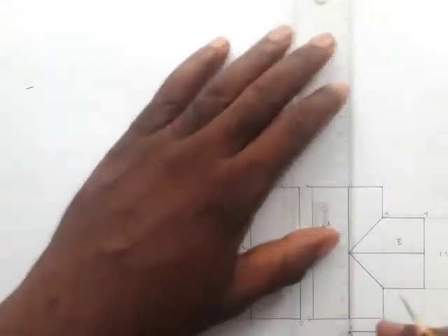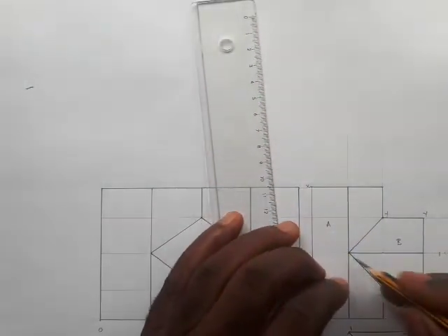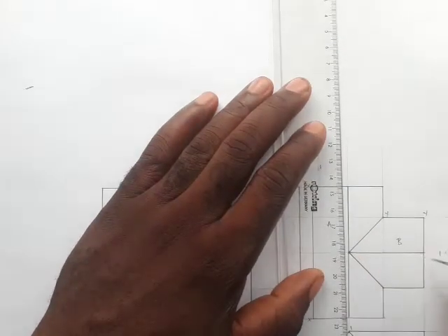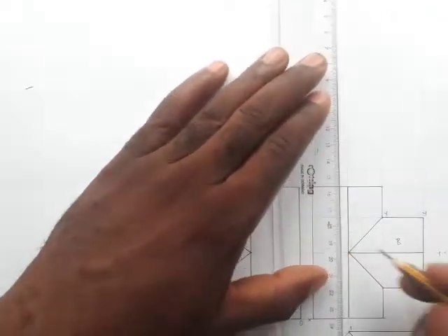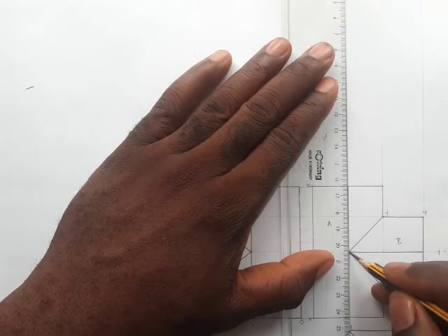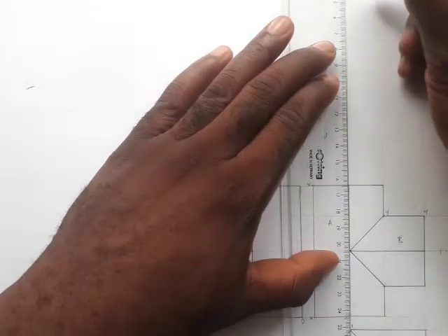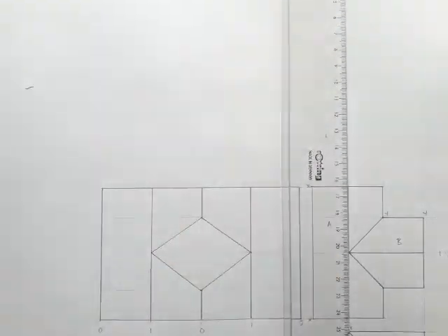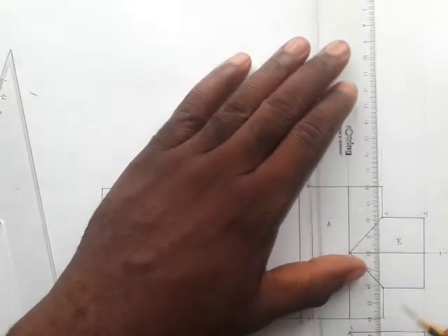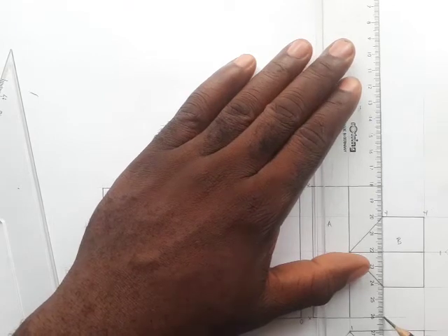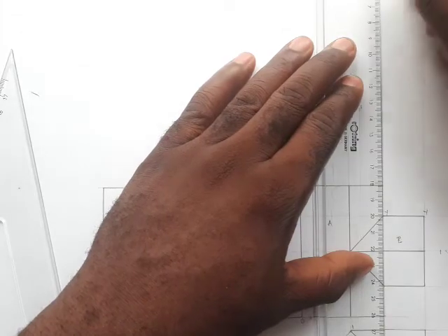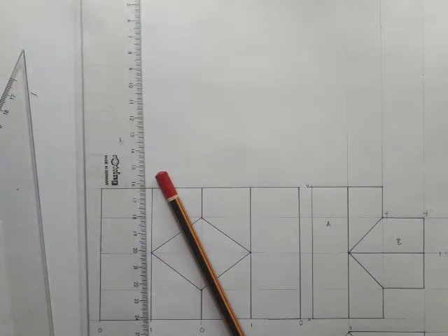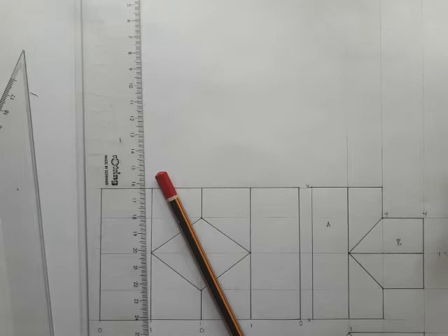Okay, so to develop pipe B, remember pipe B starts from here and ends here. So we're just going to draw from here to here. We'll draw lines up. Align your ruler with this line here and extend with a thin line. Align your ruler here with this line here and extend up with a thin line. There's no point transferring since there are already reference lines for us to draw with. So extend up. Once again, you stretch this distance of 30.